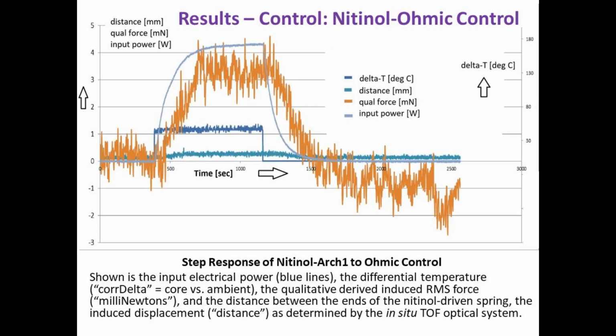Here again we can see that as a result of input power to the ohmic control alone, we develop both a delta T, which is in blue, and a qualitative force in millinewtons in orange, and we also here measure the distance in millimeters between the ends of the nitinol using time of flight in an optical system which is attached in situ.